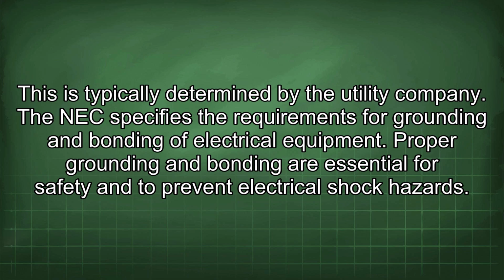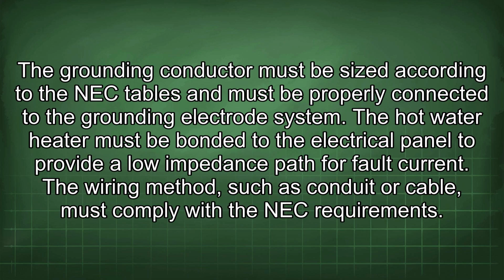The NEC specifies the requirements for grounding and bonding of electrical equipment. Proper grounding and bonding are essential for safety and to prevent electrical shock hazards. The grounding conductor must be sized according to the NEC tables and must be properly connected to the grounding electrode system. The hot water heater must be bonded to the electrical panel to provide a low impedance path for fault current.